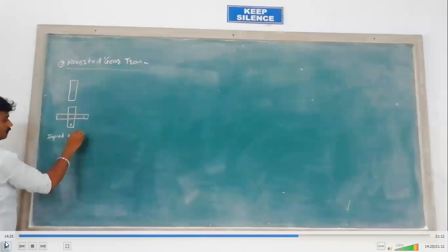These types of gear train are required to reduce the velocity or to increase the velocity of the output shaft as the input is constant. Such reverted gear trains are generally used in a clock, where the minute hand and hour hand are mounted on the same shaft, and we want different motion of the hands.